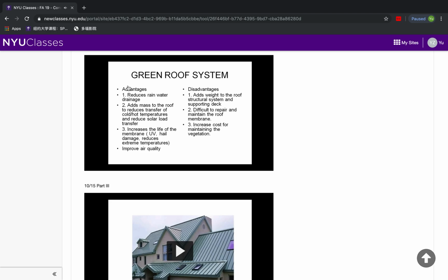All right, so again, rainwater drainage. You don't have to drain as much of it because it's soaked up by roots and plants naturally. Any excess can drain off into the sewer system, but it's wasted that way. Sometimes green roofs use the captured rainwater to recycle it into other uses, non-treated water uses like watering the surrounding greenery of the building on the first floor. It could be captured and piped down.